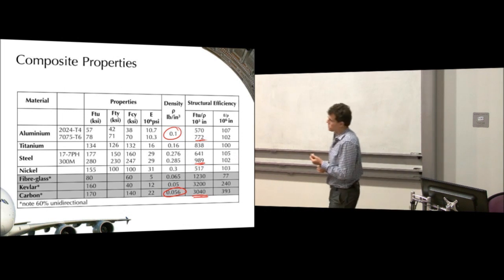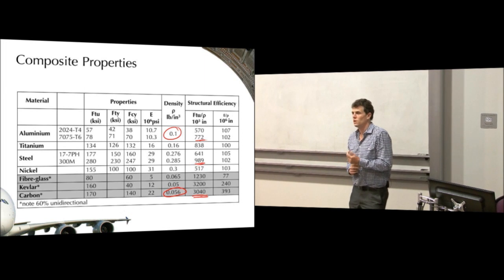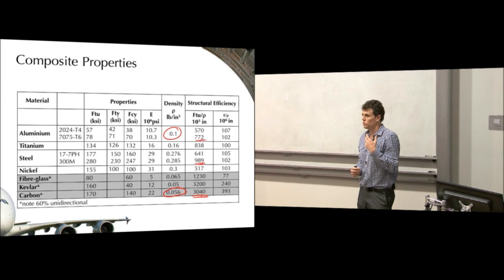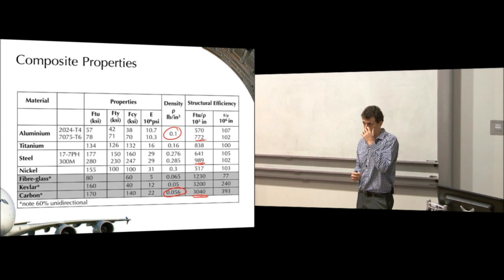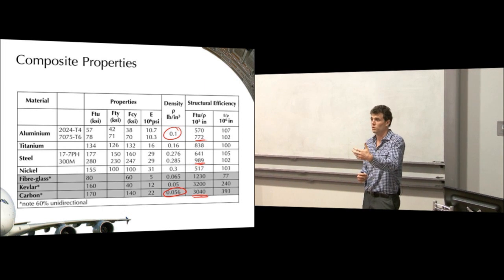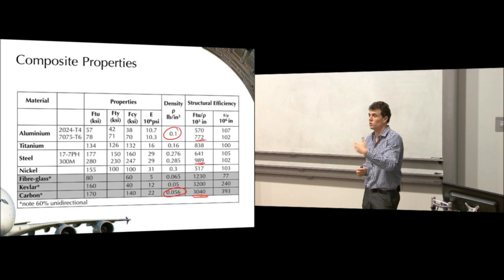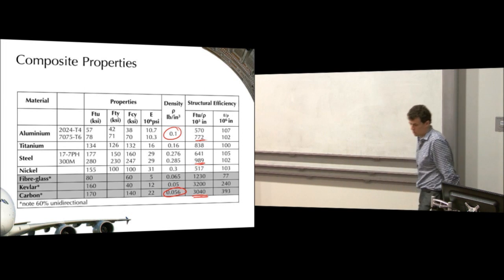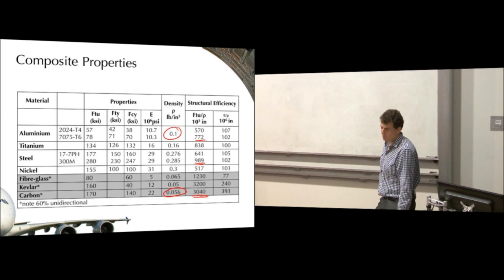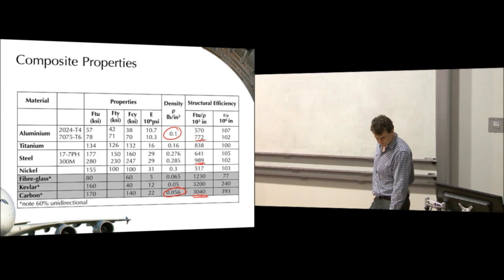One of those applications is anywhere where there needs to be no conductivity. So if you need to have a situation where you can have radar transmit through a particular piece of structure, for instance the domes at the front of the aircraft where they have a lot of communications equipment, that's generally made out of glass fibre because carbon fibre is conductive. So you create a Faraday cage that, just like having a metal plate there, the radar can't get through it. So you can put a glass fibre radome on the front. But there aren't many places that glass fibre gets used.